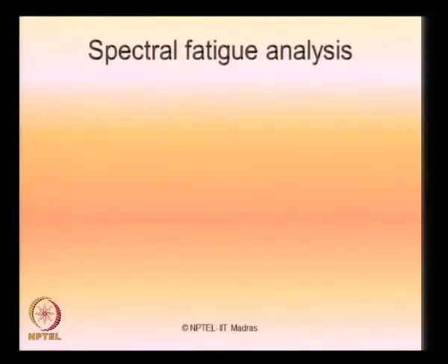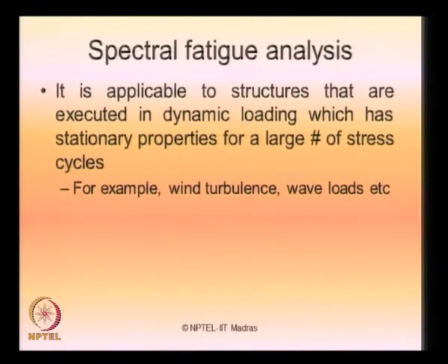Now, let us look at the spectral fatigue analysis. It is applicable to structures that are excited by dynamic loading which has stationary properties for a large number of stress cycles. For example, if you are looking at wind turbulence, wave load effects, etc., which are dynamic loading, then I must use what we call spectral fatigue analysis.